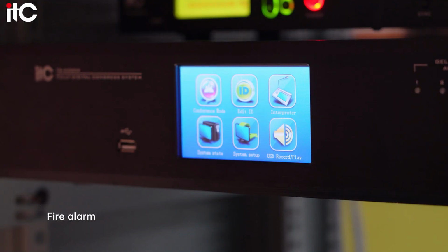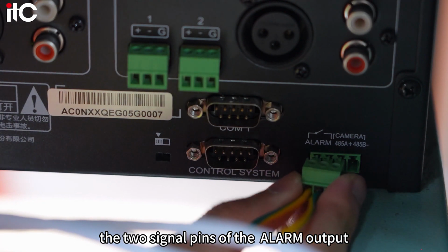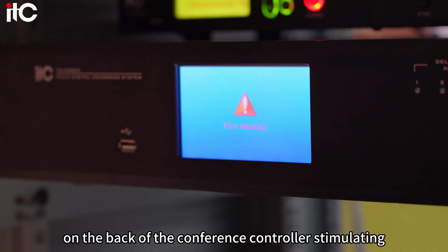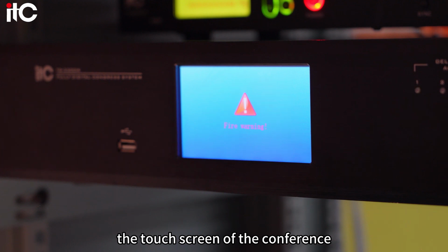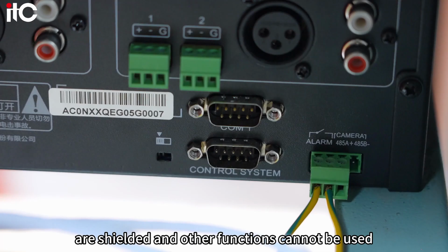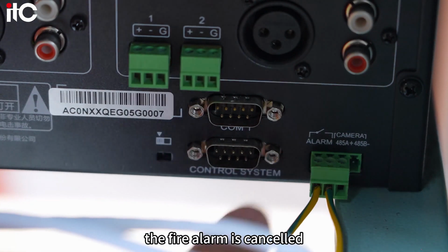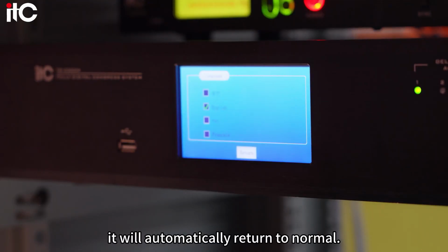So for the fire alarm, by short circuiting the 2 signal pins of the alarm output, which is like this, on the back of the conference controller, you simulate sending a fire alarm signal to the controller. The touch screen of the conference controller and the unit devices are shielded, and other functions cannot be used. When the signal pin of this interface detects that the fire alarm is cancelled, and the circuit is opened, it will automatically return to normal.